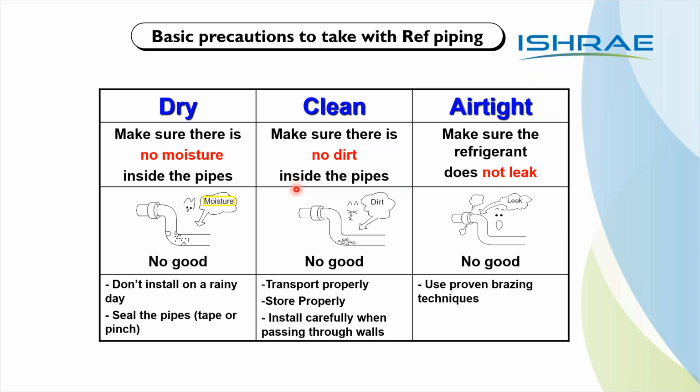It is very important for you to follow the guidelines that are mentioned, because any small amount of moisture will result in contamination of gas, and the quantity of gas is huge here when compared to another type of system. So when you are doing a VRF system, you need to take a lot of precautions, you need to take a lot of care, and never take any shortcuts, never bypass any practice.